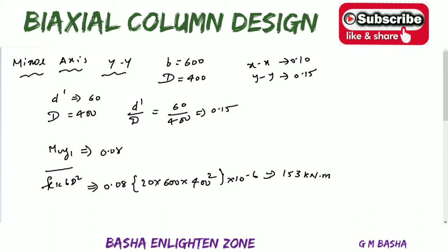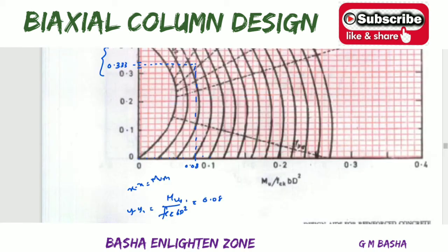Maybe somebody will choose some other values like 0.09 also. Why? Because the graph is not only related to 0.08, maybe it will be related to some other value in between these graphs, whatever value you can choose and make a perpendicular drop. So whatever value you obtain, for that value you have to find the reinforcement.